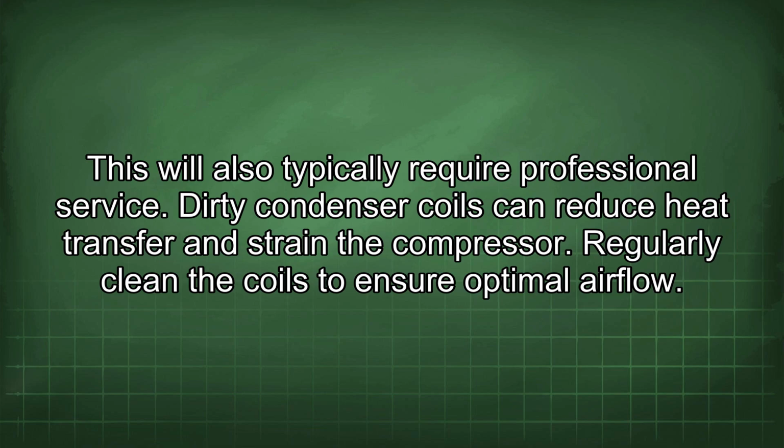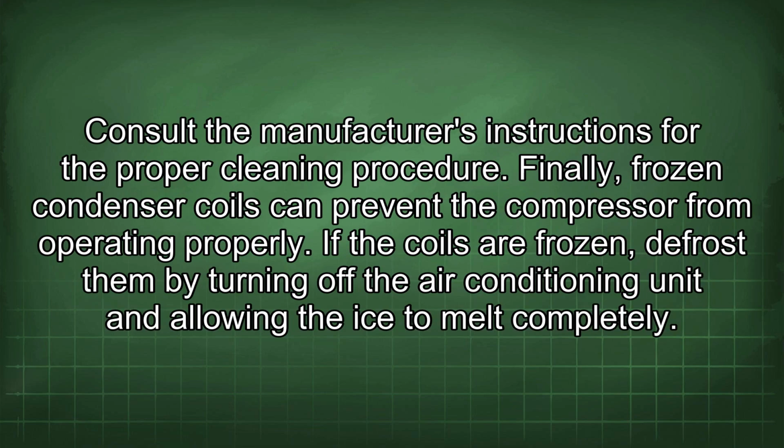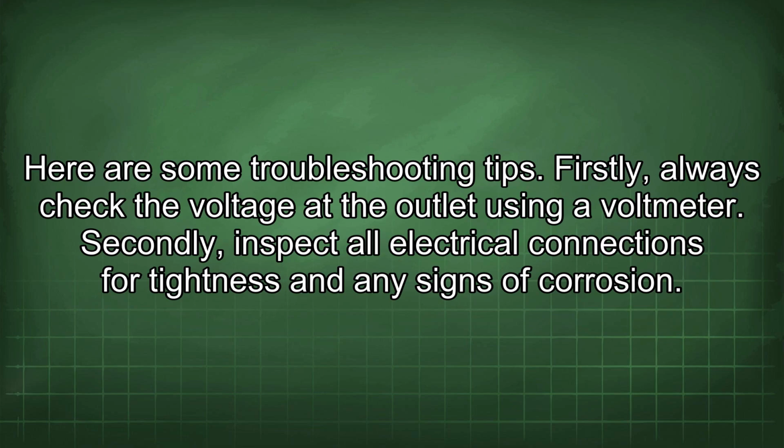Dirty condenser coils can reduce heat transfer and strain the compressor. Regularly clean the coils to ensure optimal airflow. Consult the manufacturer's instructions for the proper cleaning procedure. Finally, frozen condenser coils can prevent the compressor from operating properly. If the coils are frozen, defrost them by turning off the air conditioning unit and allowing the ice to melt completely. Here are some troubleshooting tips.